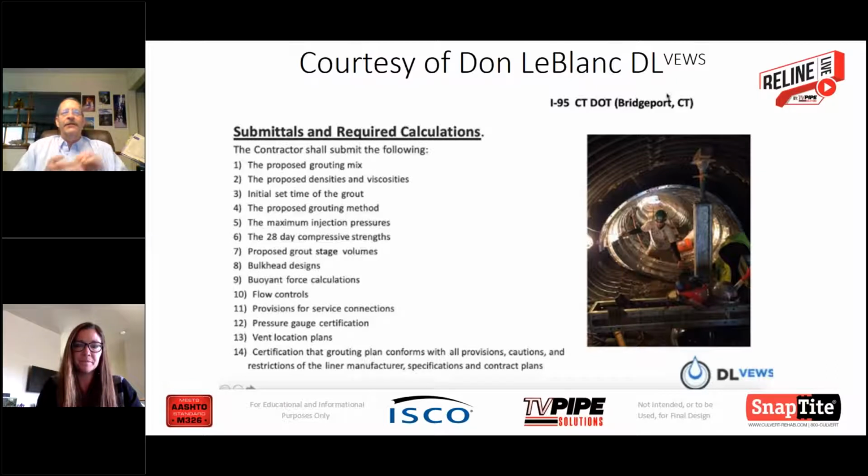Now, concrete does continue to cure sometimes up to years, but it basically reaches most of its curing process within about 28 days. And that is why most of your compressive strength calculations and design calculations are based on a 28-day break strength. Because by the time it gets to 28 days, it's achieved basically 99% of the strength that it's ever going to have. And then from there, the chemical reaction is very slow.